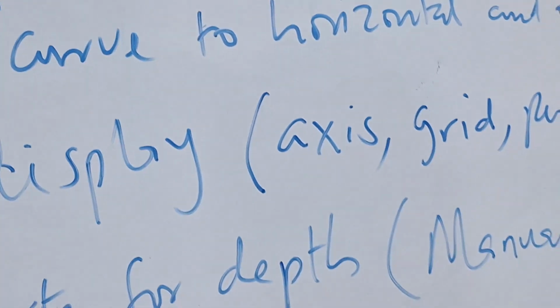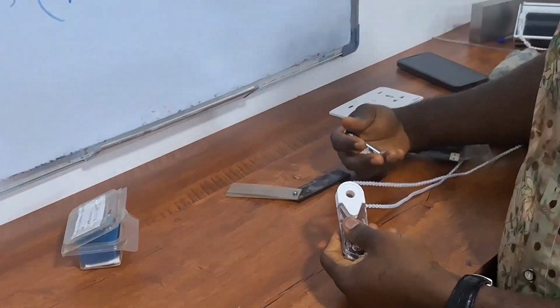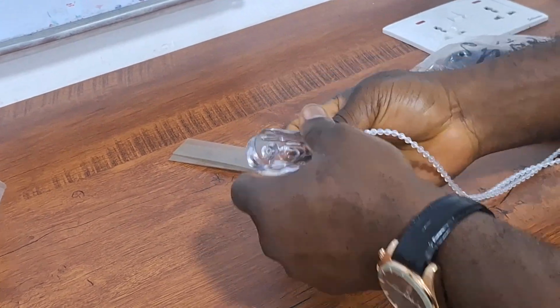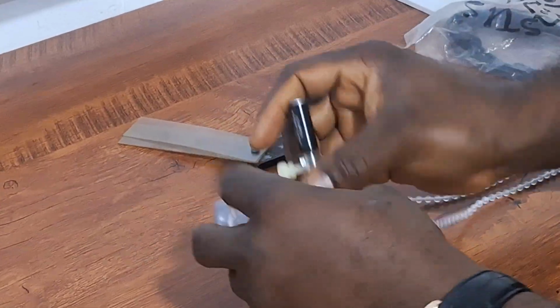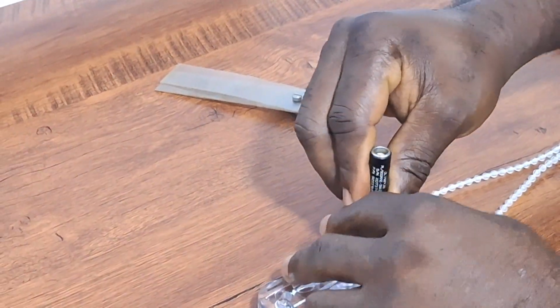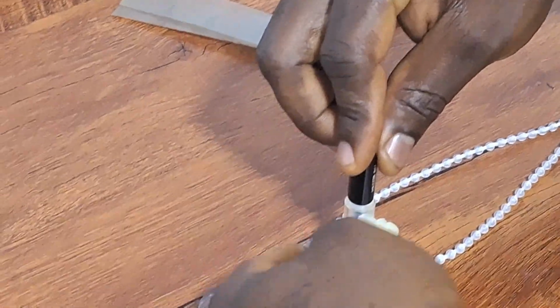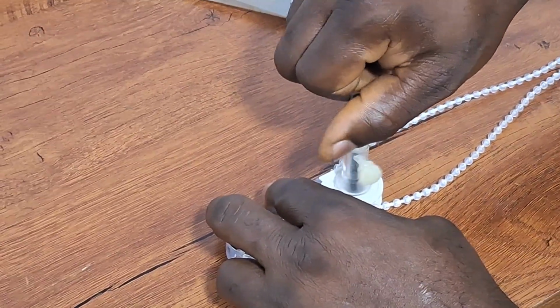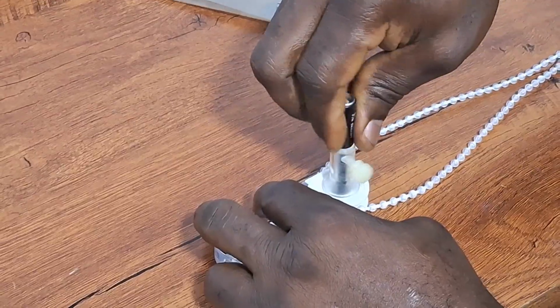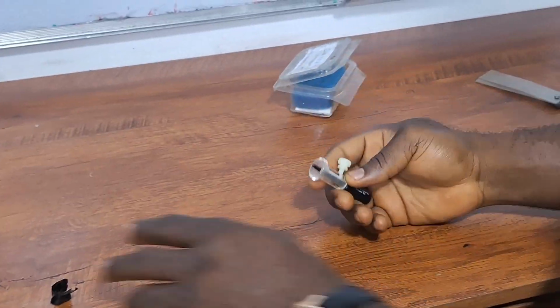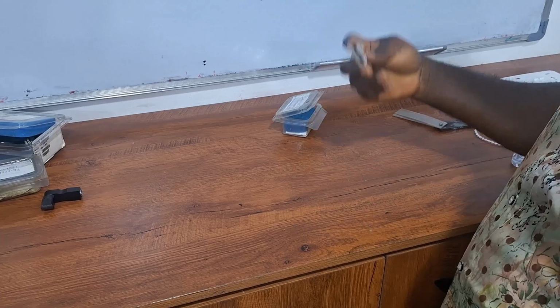So if I put it here, let's say I have this as my bolt hole and I want to inspect this hole, you see this stays on the top and the probe can then rotate freely on the inside. If this is the manual probe, you have to manually rotate it. By the time it goes round, even if it is one or two revolutions, you'll be able to see where the crack is. You can still run further revolutions to confirm it. So this is the manual bolt hole probe, but in most industrial applications, you have rotary units that you use to rotate it so that it's faster.